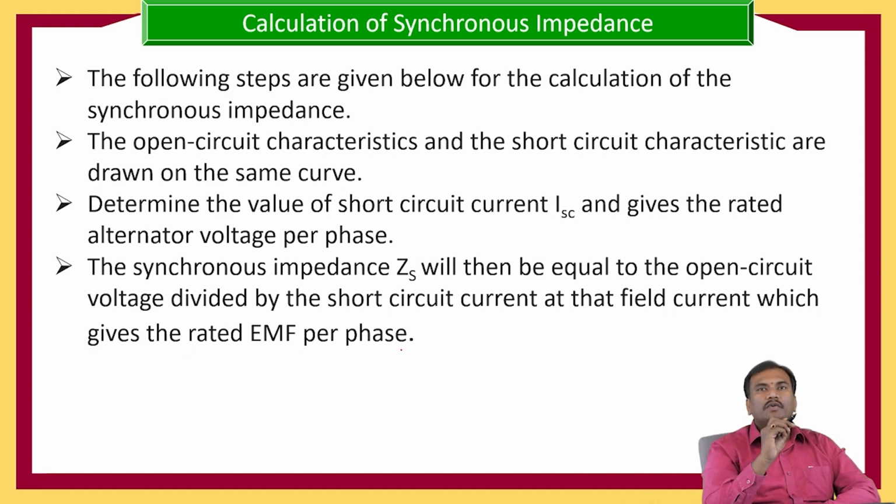Here, what is synchronous impedance? Synchronous impedance is the open circuit voltage divided by the short circuit current, at the field current which gives the rated EMF per phase.